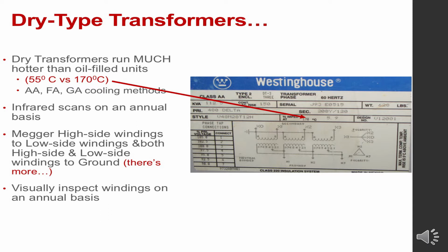And again, it's important to understand that transformers and even conductors, the ampacity, it's all about heat. So you get a transformer that runs at 170 degrees centigrade, put fans on it so that it cools more efficiently, and you can get another 25% of load out of that same transformer. So in this case, forced air systems, usually in substations, will help allow a smaller transformer to feed larger loads. This is also true for outdoor transformers in the wintertime. They'll produce considerably more output in the dead of winter than they will in the dead of summer. And some transformers use gas cooling, less common, but that's something just for mention.